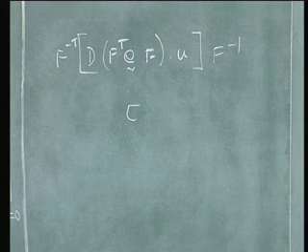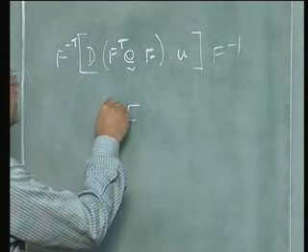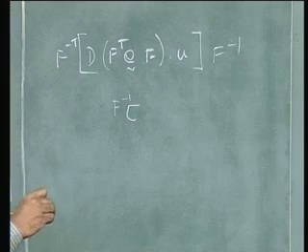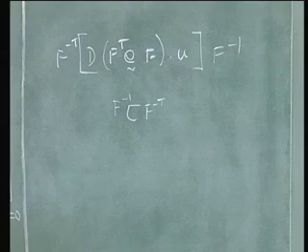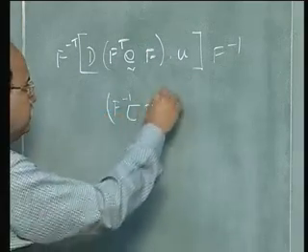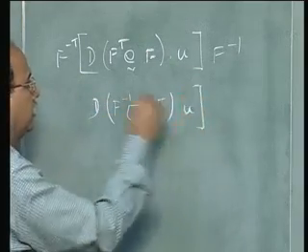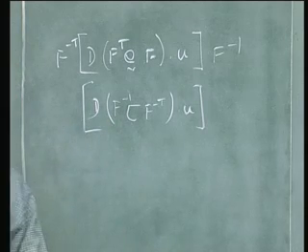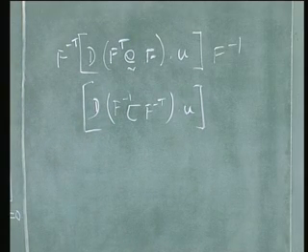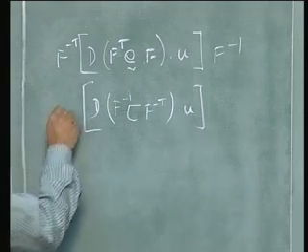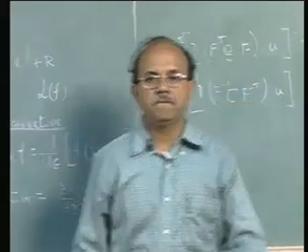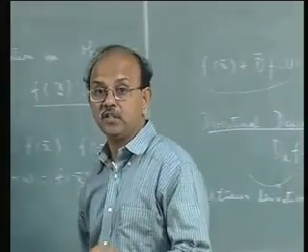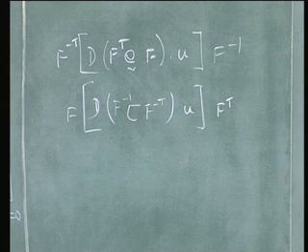The pullback operation is F inverse tau F inverse transpose, D U, and the push forward operation is just the opposite, F transpose. That is how you calculate the directional derivative of these two quantities which are referred to the current configuration.